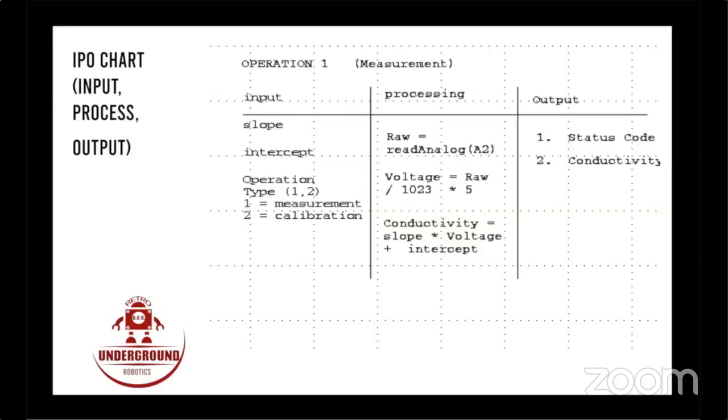When you get ready to measure something with that conductivity probe, the sensor that we have is an analog. It's not digital, it's an analog. And so we need to get an analog reading. We're going to take that reading and do a simple multiplication and division. It turns out that the Arduino analog pins deliver values from 1 to 1024, or from 0 to 1023. But basically, you get values in that range. And then once we get that value, we calculate what the conductivity is.